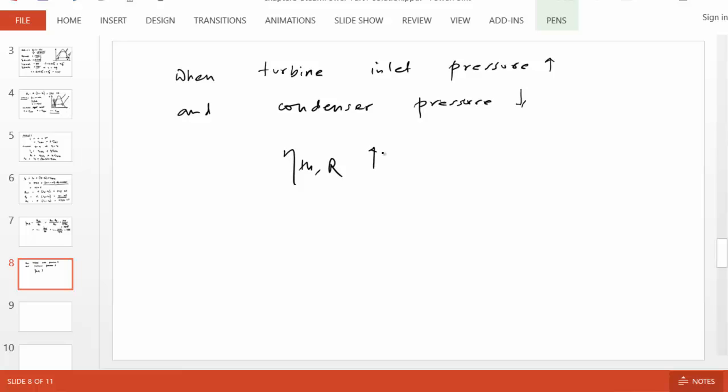As we understand the Rankine cycle, we can predict this conclusion qualitatively, very much right from the TS diagram by comparing the Rankine cycle with an equivalent Carnot cycle.